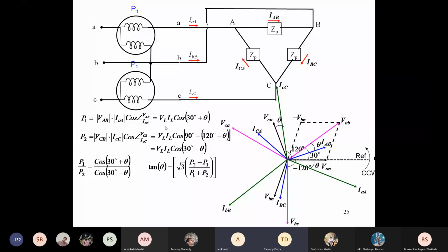That impedance, R plus jX, because of the nature of the impedance causes theta. So if you do a 3-phase balanced load in the lab and measure this power, then from this formula you can find out the power factor angle of the 3-phase balanced load.